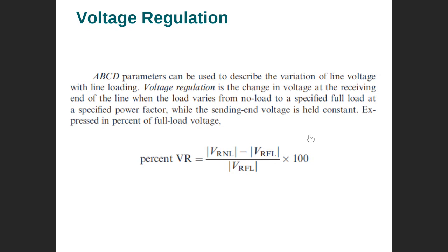What do they do? They want to add, for example, a shopping center or an industry there. They need to calculate the voltage. So they will assume that this is a full load, the shopping center, and they will see what the variation of the voltage is. If the variation is high, then they need to support the bus by compensation, by another transmission line, or by not giving the load. So they may reject having an industry or factory installed there, or a shopping center, or any heavy load.